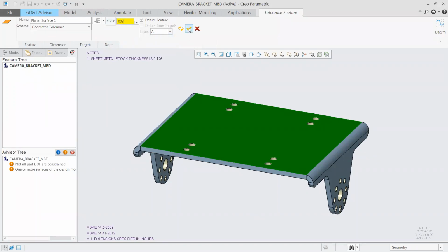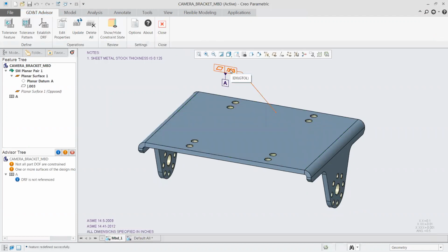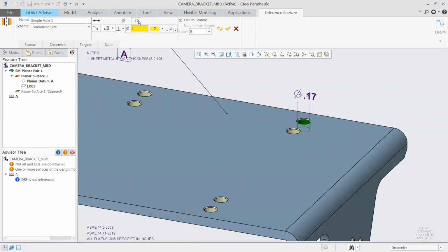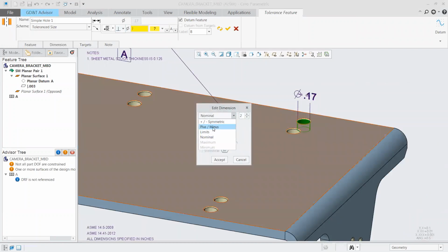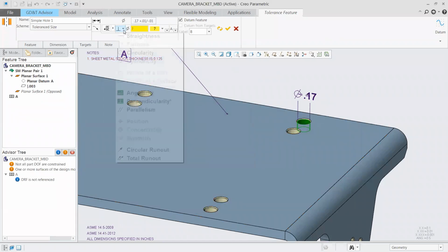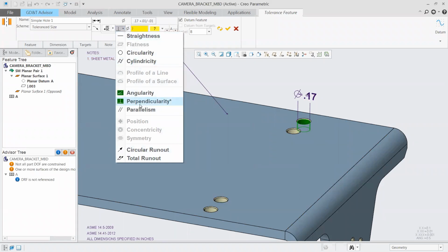All right, and now the system builds out the datum feature, and we're good to keep moving. And I can do the same type of things I was doing before, right? So such as building out the upper tolerance ranges for that hole if we need to. In this case, perpendicularity is the one that might make sense for us here. So we can go ahead and lay out our range. Go ahead and select the characteristic. We can see that, yes, in fact, perpendicularity was that. And we have a few more things that actually are available to us, which is fine. We're still allowed to use them. But in our case, we can just let GD&T Advisor let us know which particular characteristic is going to give us the most bang for our buck and really be the best type of characteristic for our particular feature.